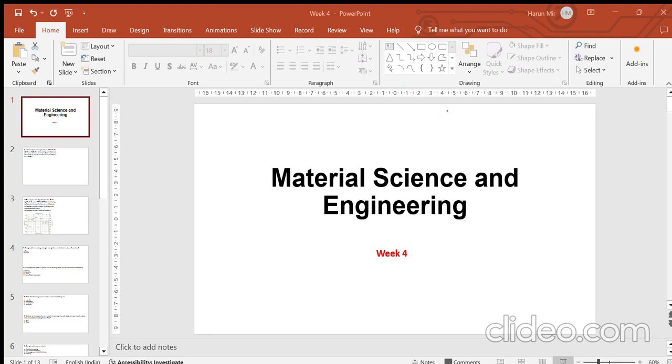But this eutectic mixture also consists of two things, which is alpha and beta. So you have two alphas, right? One is the eutectic alpha, and one alpha we will denote by primary alpha, which is alpha p, for example. So in this question you have to calculate this primary alpha, and then you have to calculate what is the eutectic alpha, which is this alpha.